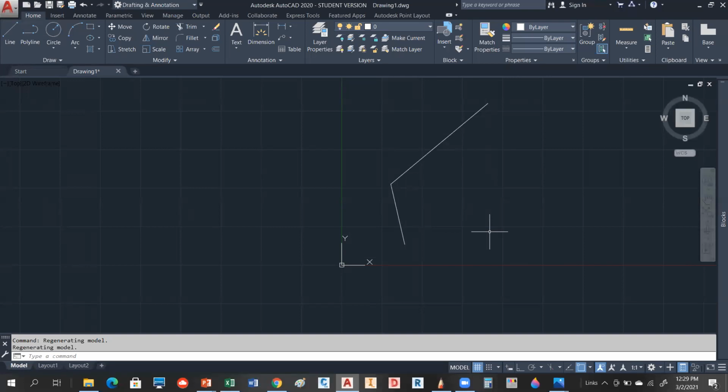All right. So Jake, you asked the question initially. Does that help for AutoCAD? Yeah, so if my starting point, if I were just to put in 10,000 and then 1,200, it would start me at that point. I don't need to set the X or Y or anything like that. Right. Although if you just type in 10,000, 1,200, you're actually going to be X and Y, so you're going to be reversed. Okay. Oh, that's why. Okay.